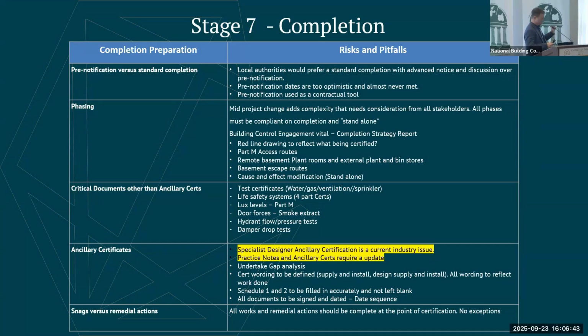So when you lodge, you are effectively done. When you get validated, it effectively means whether or not it's going to happen, a member of the public can occupy that building that very day after you get your validation cert. Or the way it's been communicated to us from building control is that's our level of expectation. Yeah, you could be painting. Yes, you could be landscaping, but you can't be in there doing fire doors and fire dampers and paving. So it's that level of completeness conversation needs to be a frank conversation prior to completion.